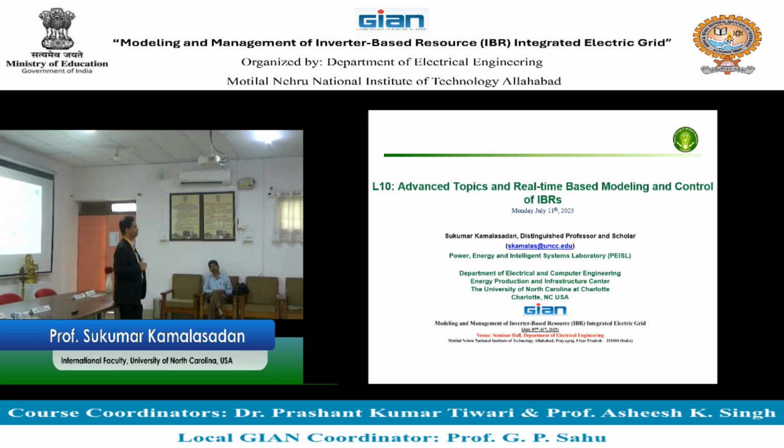Such a controller, connecting and taking the angle from the grid, is called grid following, because it is following the grid. If the grid is not there, that control architecture has to be switched or changed to track the voltage and the angle, and that is called grid forming. And it is done through three different methods. One is called droop, second is called virtual synchronous generator, third is called the oscillator technique. And I gave a storyboard of each one of those methods.